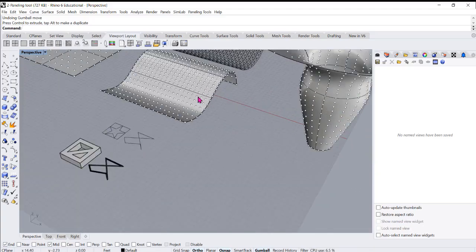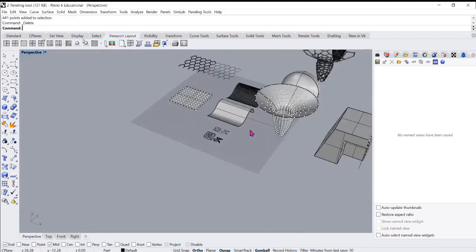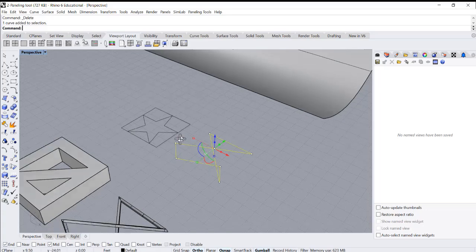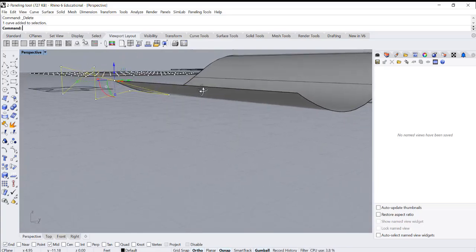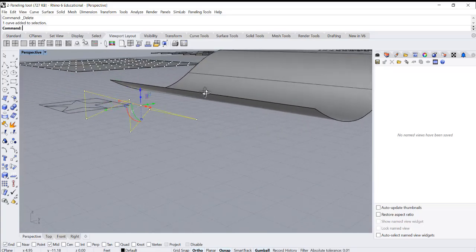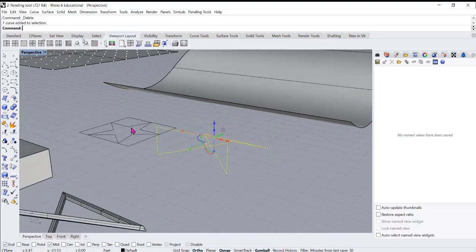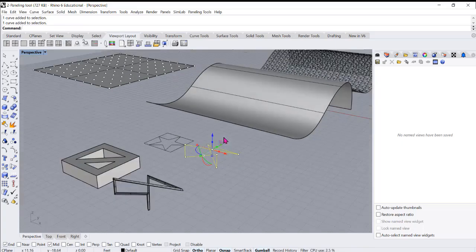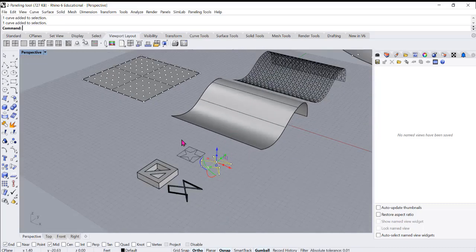Now, in a case where you have a pattern that's made of curves, but as you can see in this case, it's not flat like the star. It's going in all three axes, X, Y, and Z, not just X and Y like this one right here. So this one is going on three axes. Then for those scenarios, this will not work. It will put a flat copy.